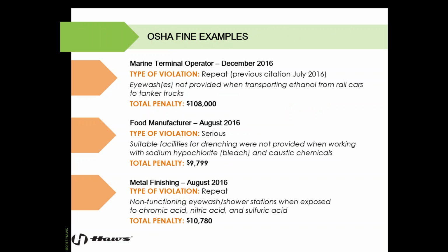Here's a couple examples of recent OSHA fines specific to emergency eye washes and showers. A marine terminal operator in December of 2016 had a repeat violation, and again, those typically will see some higher or more hefty fines, for not providing eye washes at all when transporting ethanol from rail cars to tanker trucks. We saw the total penalty of $108,000 for that missing eye wash or eye washes.